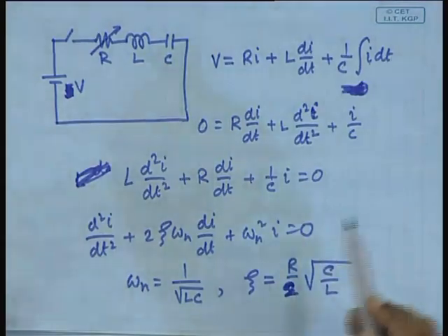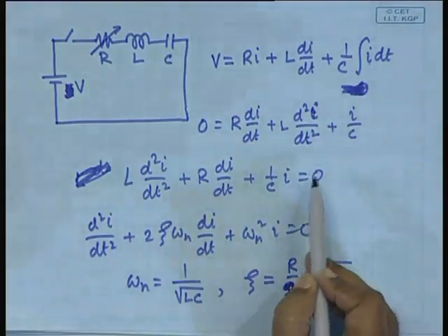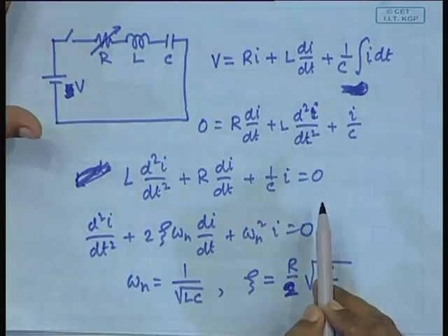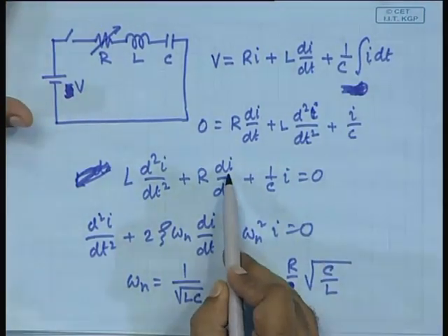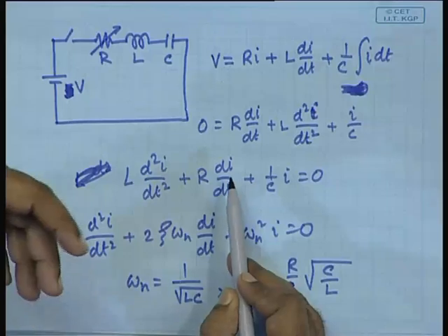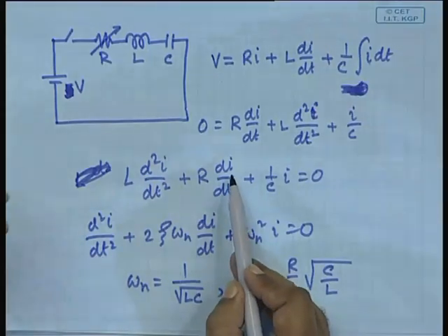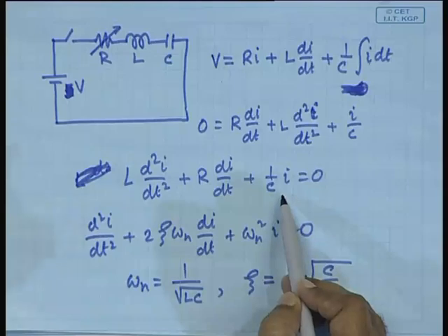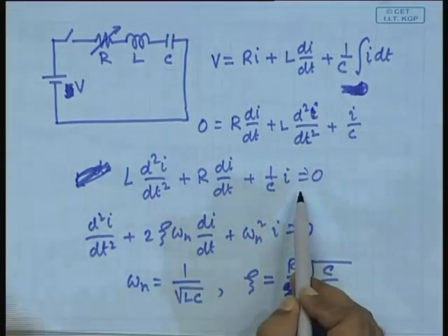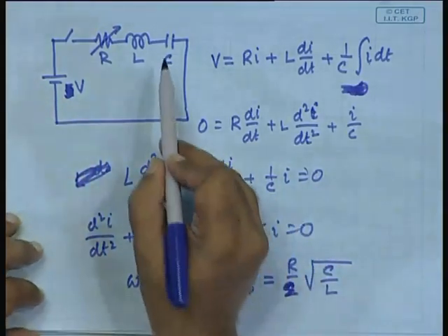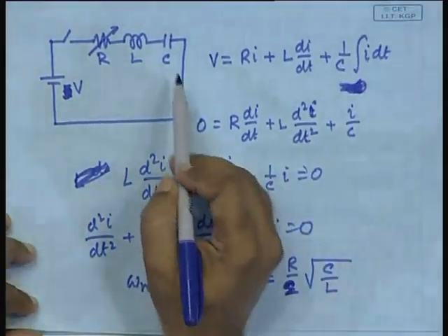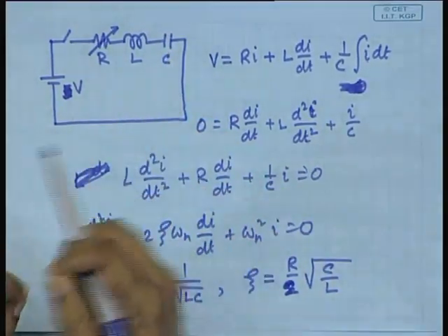The way we did it was, if you have this equation, then you can write it in an equivalent first order form, in which I will be one variable, and the integral of I dt, Vc, will be another state variable. So, you have two state variables, the Vc and the I. If you consider Vc, what will be the equilibrium point for Vc?